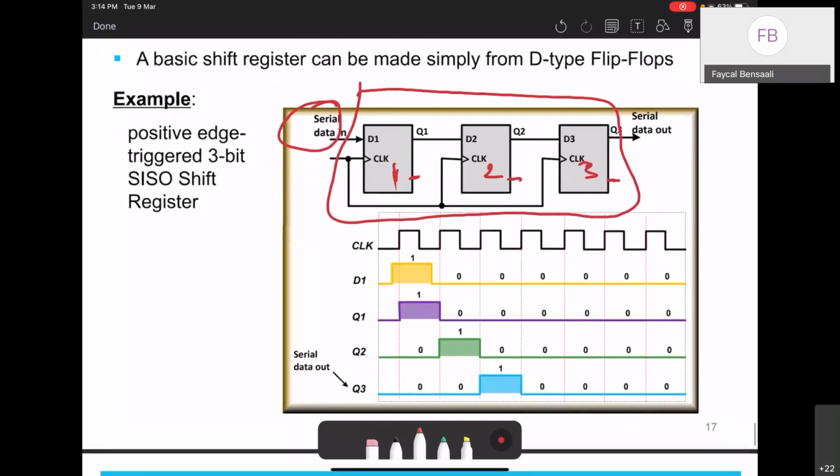If you observe this circuit, let's say I have this scenario for the input D1. We start with 1, and then it stays 0. Of course, you can have different scenarios. Now, what do I get from the first Q? Again, I didn't specify if this is rising edge or falling edge, which means all of them are rising edges, the default one. So if I take the first Q, Q1, we say Q follows D. Because I'm working with Q1, what is D1? It was 1.